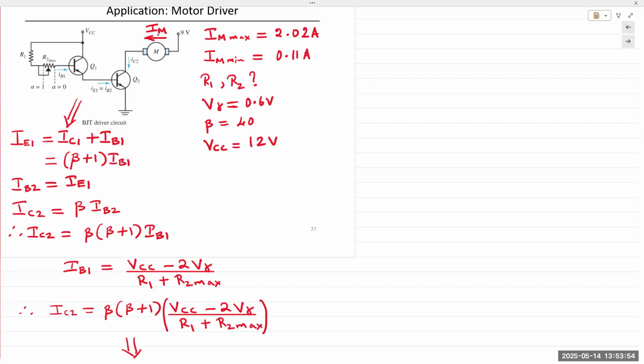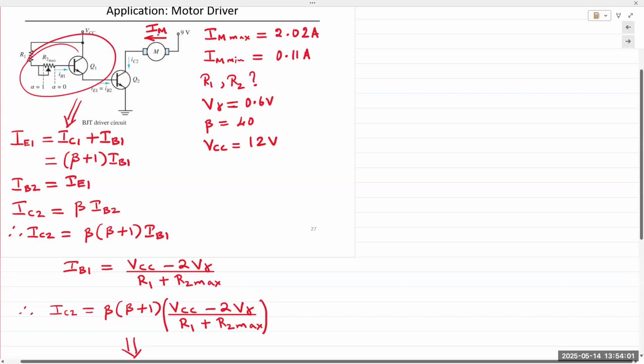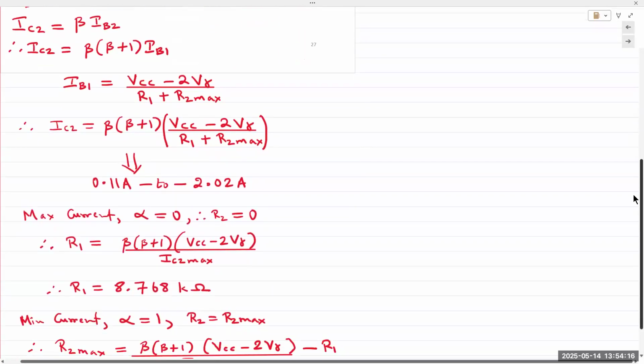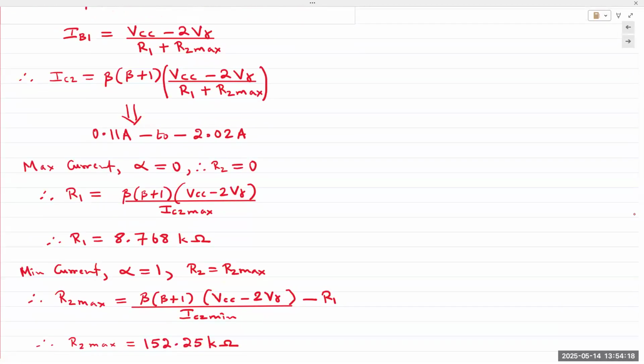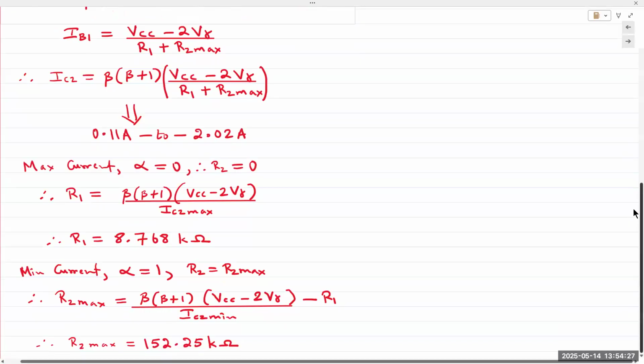So in this motor, we need a large amount of current to flow through, which cannot be handled maybe by just a single transistor. So we take the previous circuit and drive the output into the base of another higher power transistor. That transistor is able to support 2000 milliamps, or 2 amps, of current, okay? There are some equations that relate both transistors. It's basically the output of one transistor, IC1, is equal to IB2, okay? IC1 is equal to IB2.